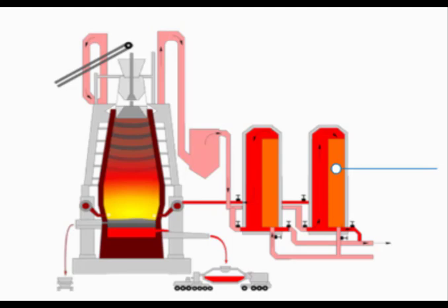When sufficient heat has been absorbed, the stove is put on blast. In this mode, no combustion takes place, but the cold blast air is forced through the stove and absorbs the heat to become hot blast. This is then mixed with the cold blast to bring it to the right temperature, and as we see here, there will be cold blast from the bottom. Then it is forced into the blast furnace via the tuyeres. There will be the hot blast main, the bustle pipe, and the tuyeres here.